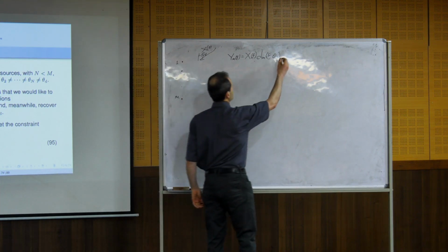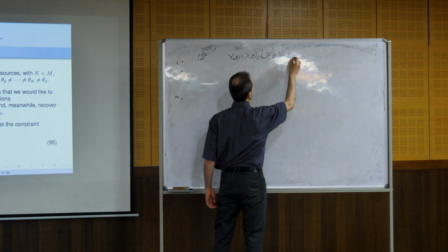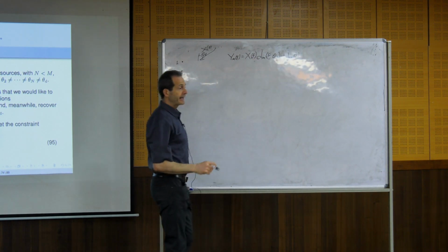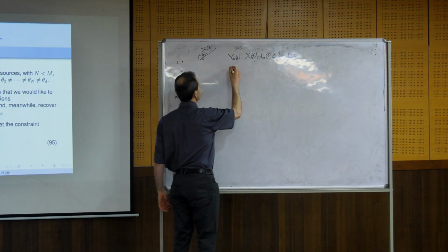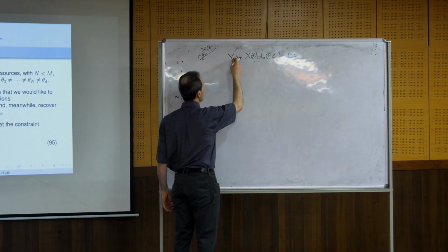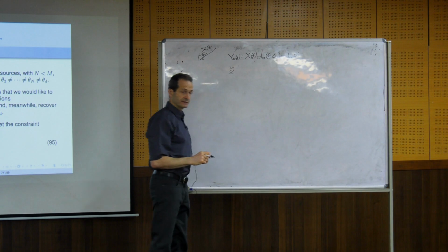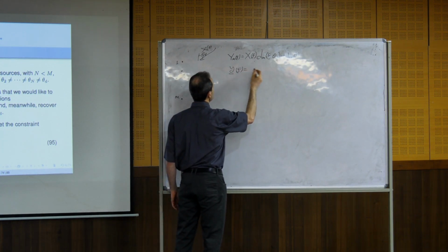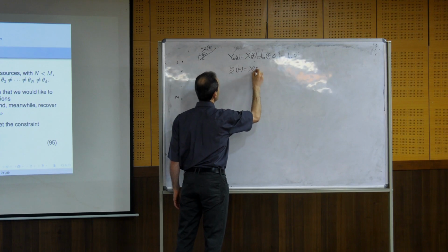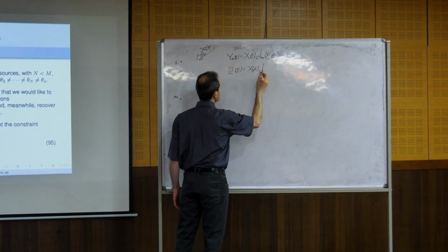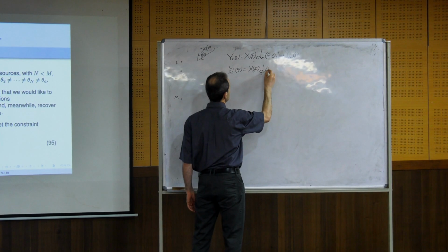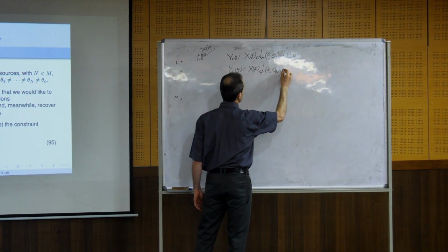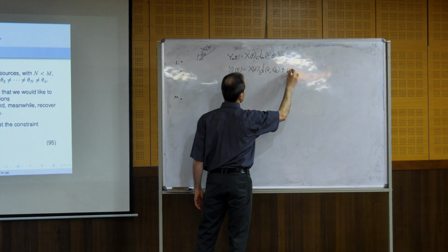Plus noise. So this is sensor number M, and then we can define a vector of M sensors, for each frequency f, which is X(f) multiplied with a steering vector d(f, theta d), plus a vector of noise.